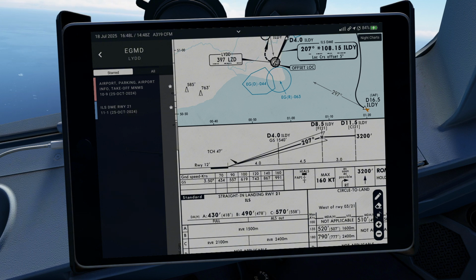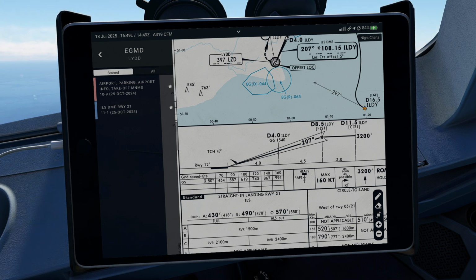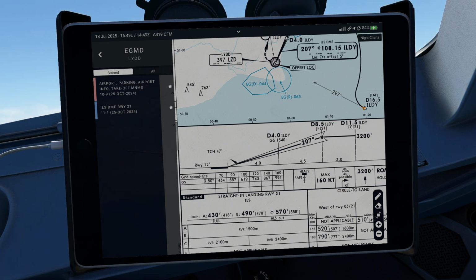The decision altitude is actually evaluated, ensuring the pilot has time to visually align with the runway. No autoland capability is authorized, and this keeps the approach precision in guidance type, with both localizer and glide slope, but operationally handled more like a non-precision approach, as we will see later during the approach.